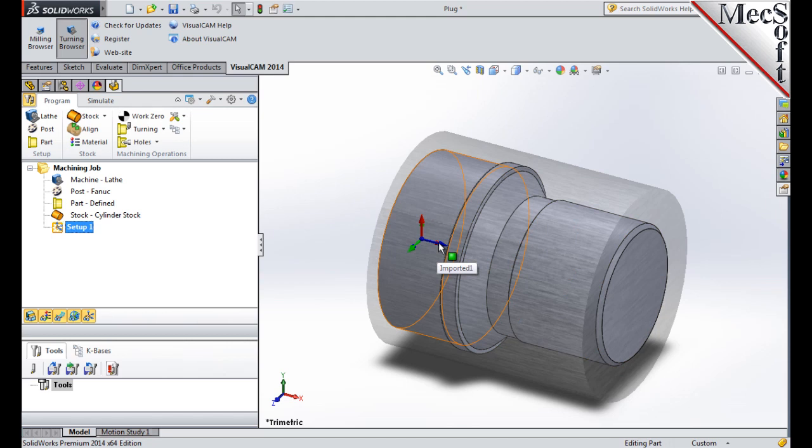Secondly, the axis perpendicular to this axis, along which the tool travels to cut into the stock, is designated as the x-axis. So, the part and spindle rotate about the z-axis, and moving the tool along the z-axis provides the direction of feed, and moving it along the x-axis provides the depth of cut.